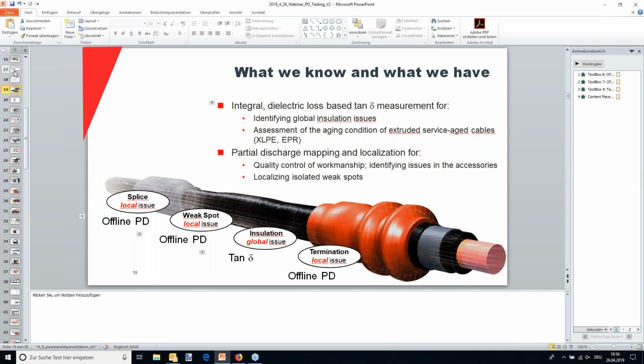So what you can pretty much say is online versus offline. Online is a tool for substation monitoring mainly, to monitor concentrated assets under system operating conditions, vibration levels, voltage levels, all these things under operating conditions, but you cannot vary the system voltage.